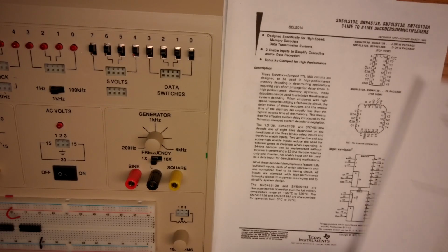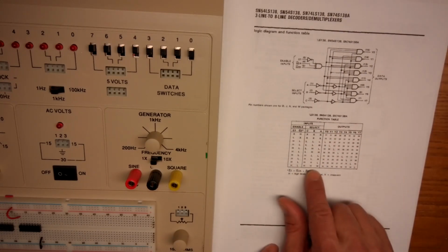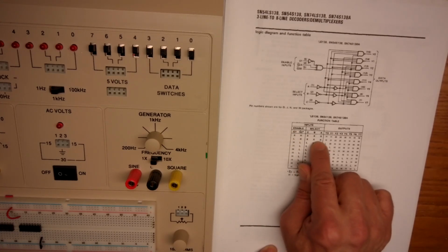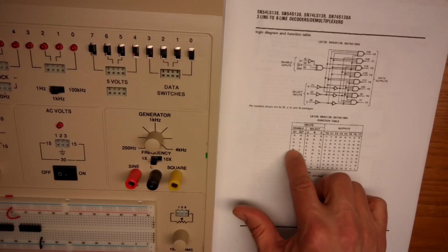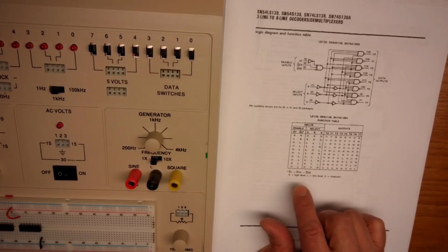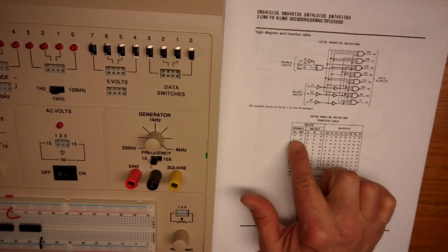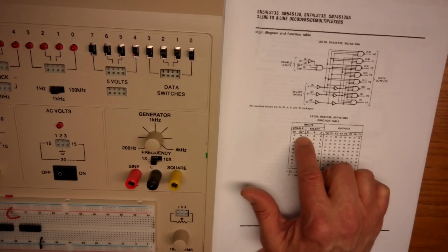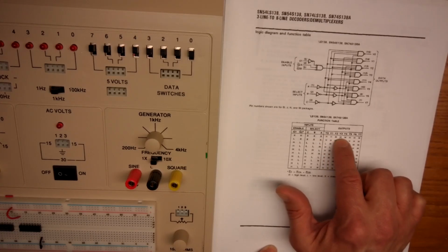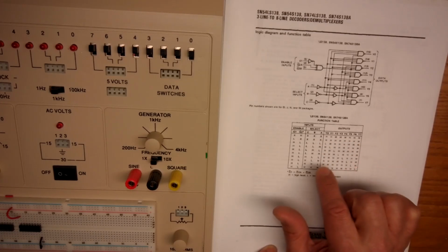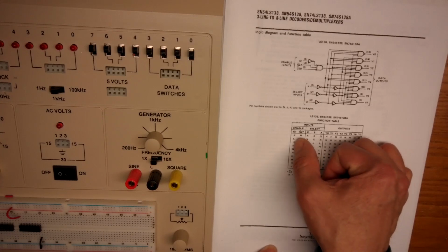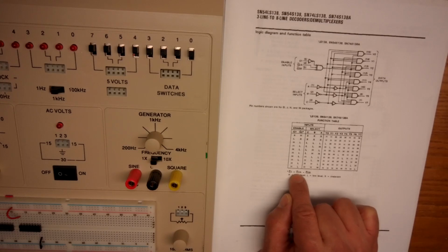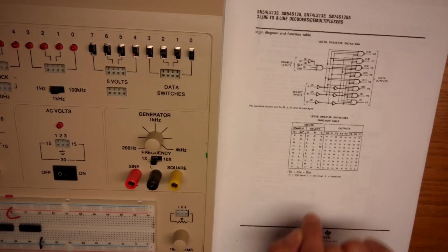Okay, so if I go here, I can look down and notice if G1 is low, then my outputs are all high. That means I haven't enabled it. So I need it high for it to work in its normal mode. And if you look here, if I set G2 high, that's going to set all these high also. So really I want my G2 low and my G1 high. And I'm going to look down here, and G2 says that's equal to G2A or G2B.